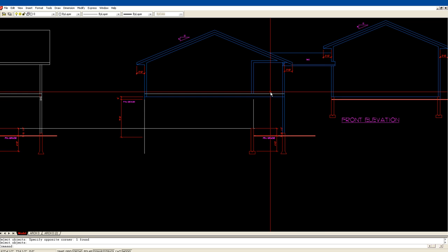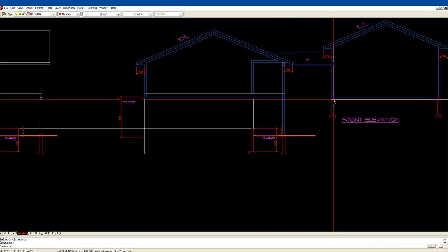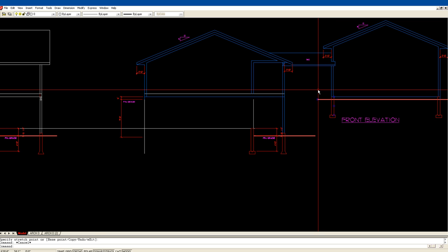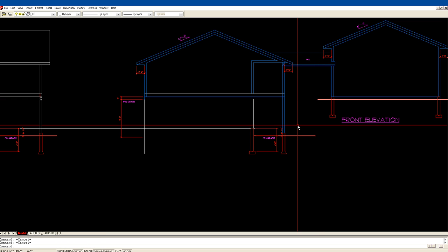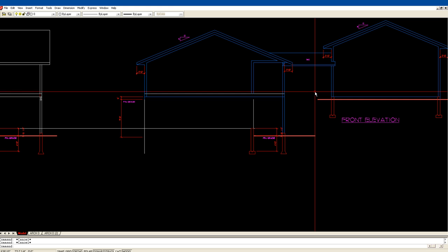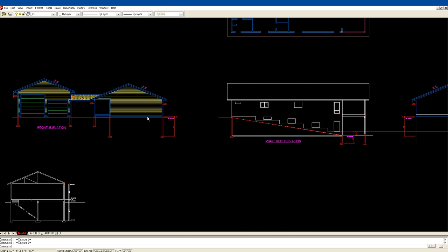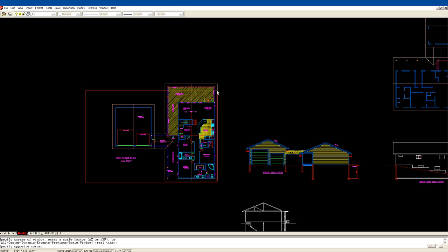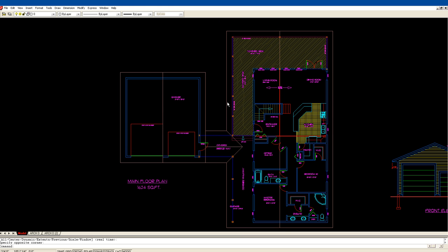This is the deck at the side of the house. From this point right here, the grade, he's going to have to dig down in between these two, or put a retaining wall in. And there isn't a heck of a lot of room there. We've already discussed this with the client. So we're looking at this area right in here where my crosshairs are twirling. Now there's the deck, and the ground wants to drop below, but if he does the same thing to his garage, of course he's going to have 10-foot high concrete walls at the back of his garage.